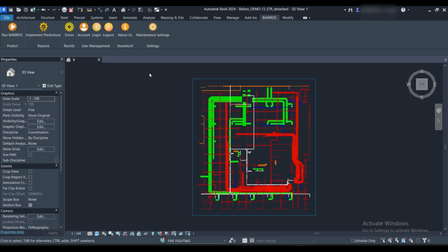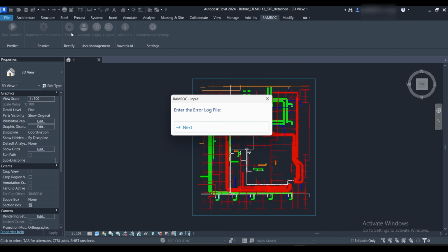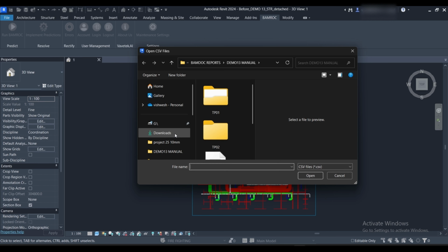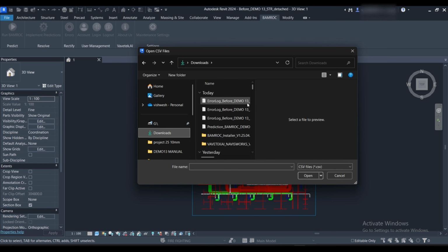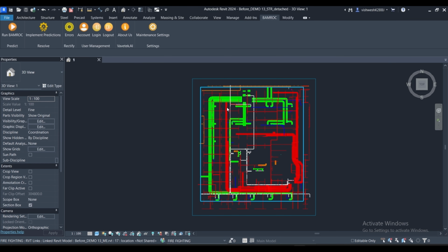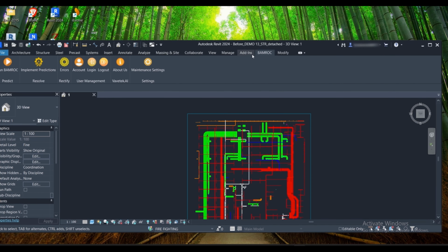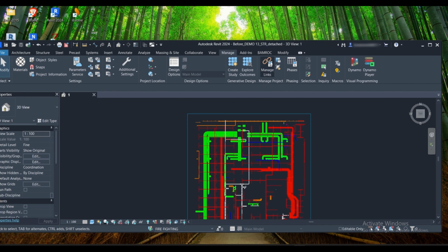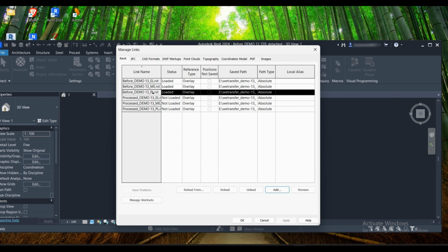Let's say I go and select the plumbing file. Since I know it's involved, I'll unload the plumbing file here first. Why? Because we need to open these models individually to inspect errors. Next, I'll open the PL model separately. I'll make sure to detach it from Central, and yes, the worksets are available. So now I have my PL part open.